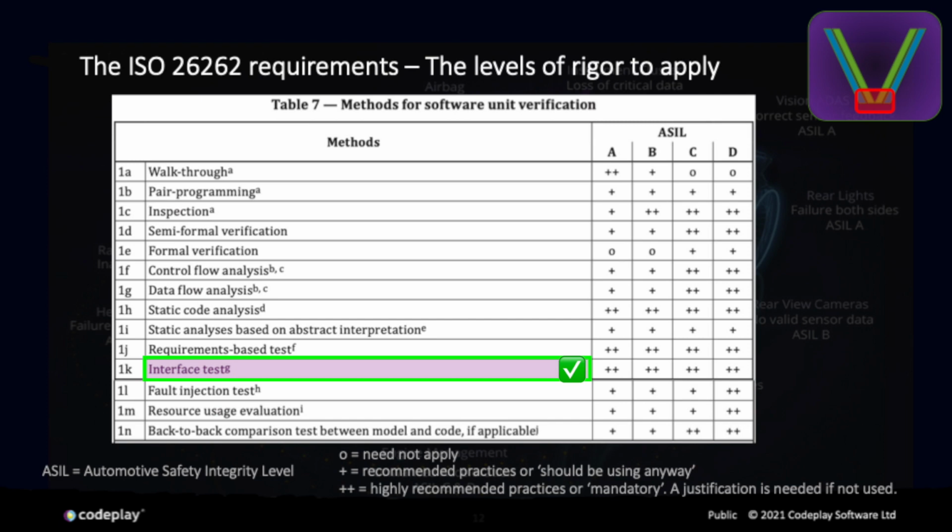Now, other parts of the stack may present more of a challenge because the requirements are not well defined or validated. An important item in this table is fault injection, and I've marked this as a challenge. I've marked it as a challenge because it's not generally considered as part of the design phase of the stack's development. And yes, you can and should carry out black box testing, but ISO 26262 is looking to see if code within a component is resilient to spontaneous random faults and single points of failure, and that the whole system is not brought crashing down but enters a deterministic, safe operational state.